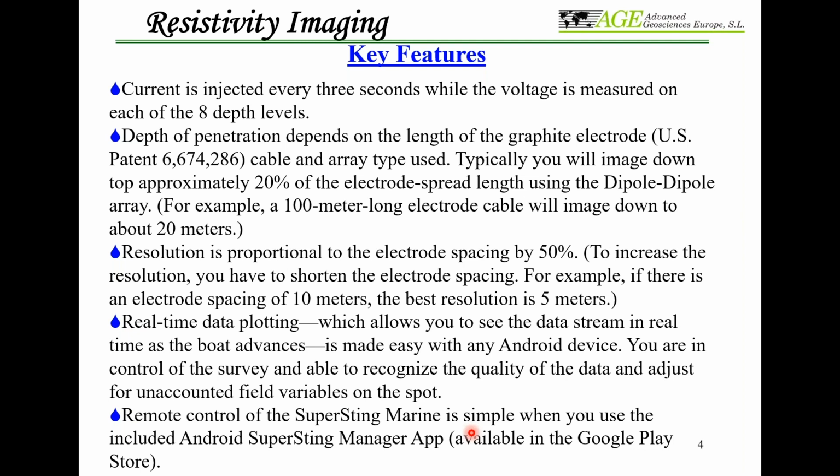So you make sure that your data quality control is done during the field data acquisition. That will save your money and time. If you make some mistake or error in this kind of study, as you know, you need to go back and repeat, which is sometimes not possible or costly.